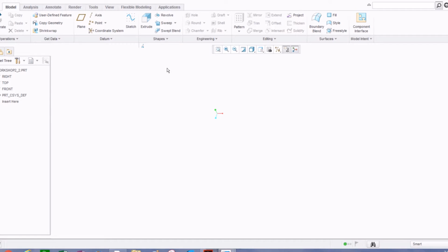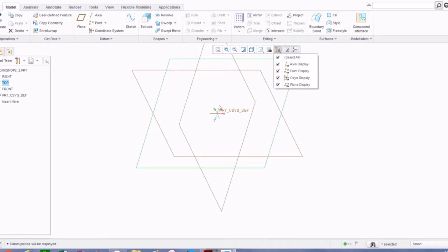But what I've decided to do here is we're going to start with this object using just blends. Easiest thing we can do here. So let's go ahead and click the top plane. You can't see planes on there, so we want to go ahead and activate those planes again. Come up here to the center and select them on. You can see now it shows our plane there.